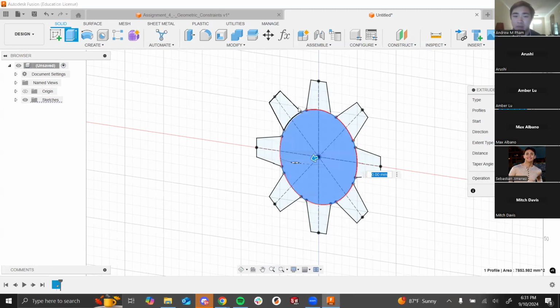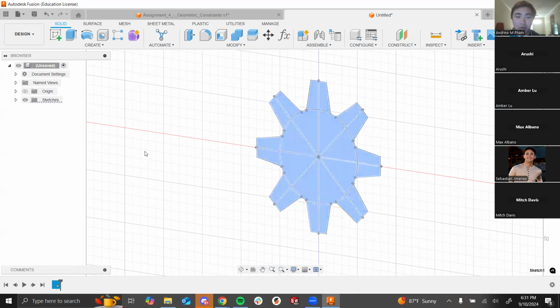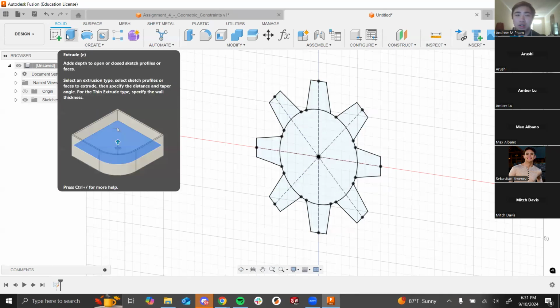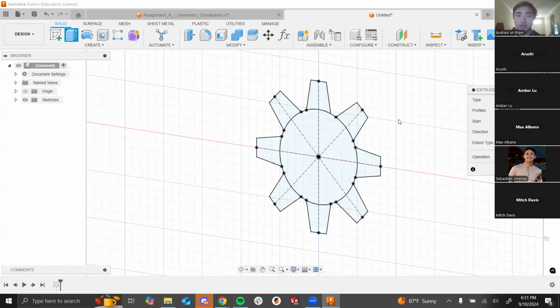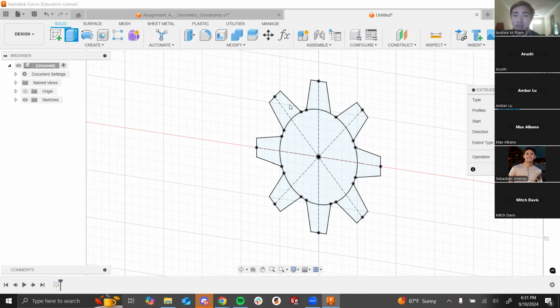But in this case, I'm just Wait, can you go back over extruding? Yeah. Sorry. No, you're good. Again, you want to make sure you exit your sketch. There's a green check mark in the top right, and then you extrude it, next to the sketch button. Extruding just takes your 2D sketch and pulls it into 3D.